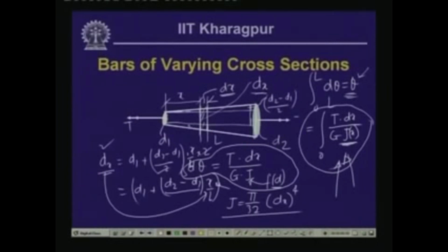Now, if we have a varying twisting moment, instead of a constant twisting moment in the bar, then over the segments, as we have done in the past, if we have a non-uniform twisting moment, between two such twisting moments we take the free body, find out how much the twisting moment is, and in that segment again we compute the stress. We calculate the maximum of the stresses in these zones, and the maximum of these maxima will give us the maximum possible shear stress in the whole bar.